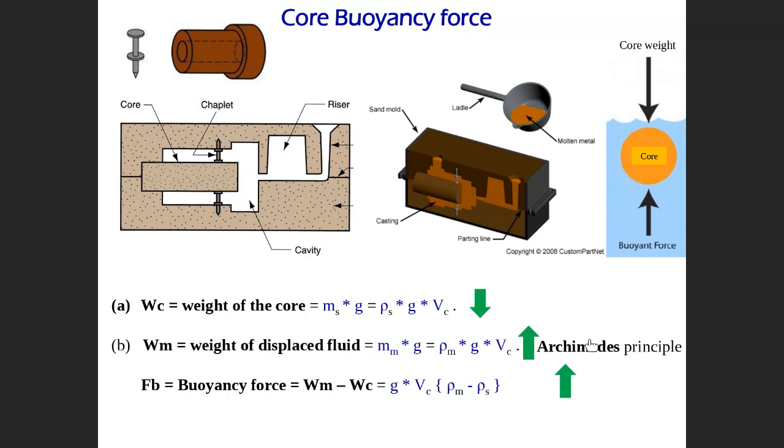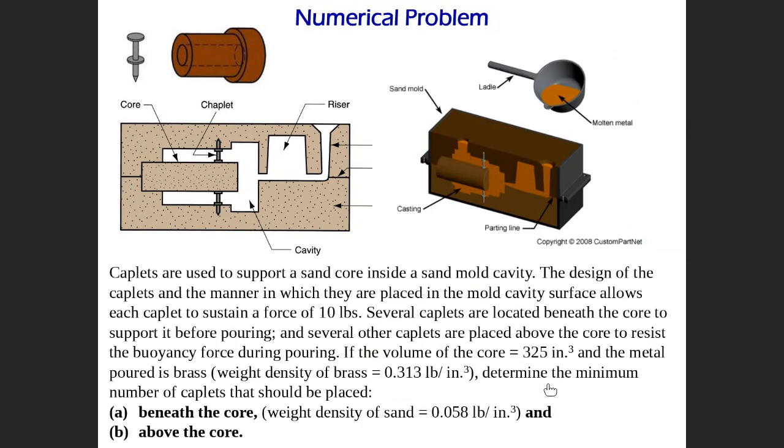So the rule is that the liquid fluid pushes this one up with a force equivalent to the weight of the displaced fluid that was supposed to be here, which is equal to the mass of the liquid that was supposed to fill it, multiplied by gravity acceleration. That's it. Did you get it? Yeah, it's clear. Let's take an example and see how to apply these fundamentals or rules.